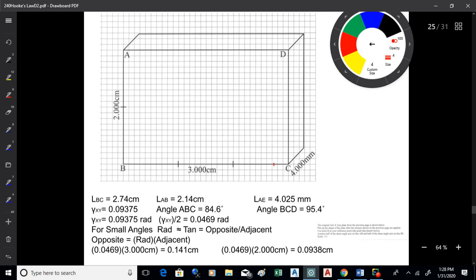Each one of these small boxes is 1/10 of a centimeter. So just the normal or axial deformation puts it right about there. But it's not going to stay there. See, that's part of the story. That's this bit. But it's also going to rotate a little bit. It's going to kick up by 0.141 centimeters. So that point is going to end up right there.